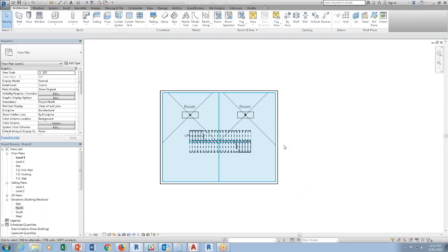What it does is, if you run into problems where, when you place a room, it's always at 0, Revit would just not calculate that if it's at 0. So if you tell that level, computation, I want to calculate all the height that's above 4 feet, then it will start to put in that room. Just in case you run into this problem where rooms are not closing properly, first thing is to select all your levels and set the computational height, just make it like 4 feet. And then that should resolve some of this issue.